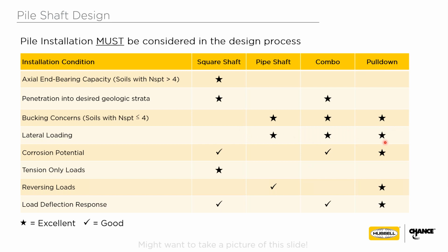It comes down to how much resistance you can develop with the stiffness of your shaft and how much passive resistance that particular diameter shaft will provide. Obviously, with a V zone open structure, you may need additional or more supports than you would for, say, an A zone, which doesn't require as much elevation, and you're not having to worry as much about a storm surge in an A zone area.